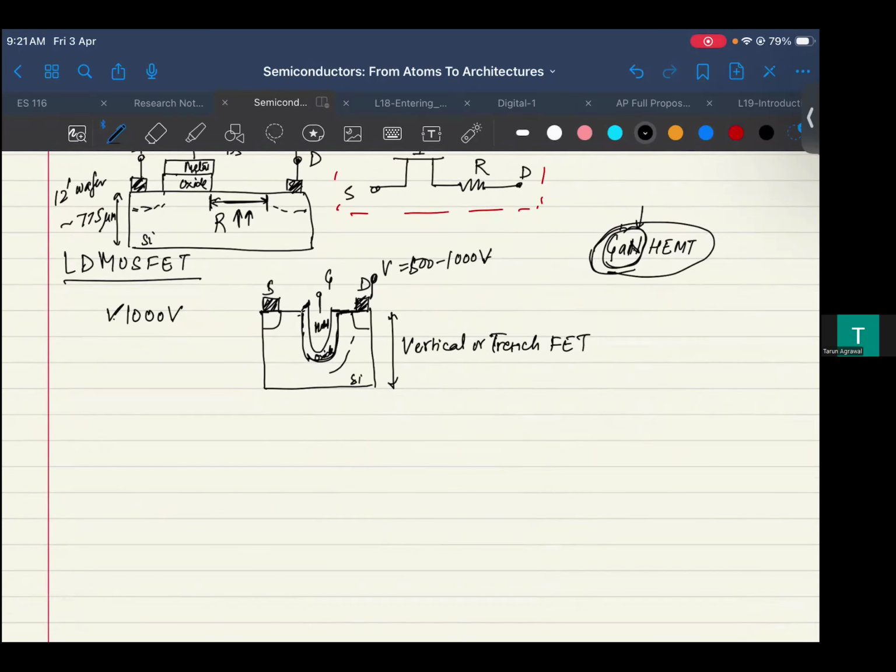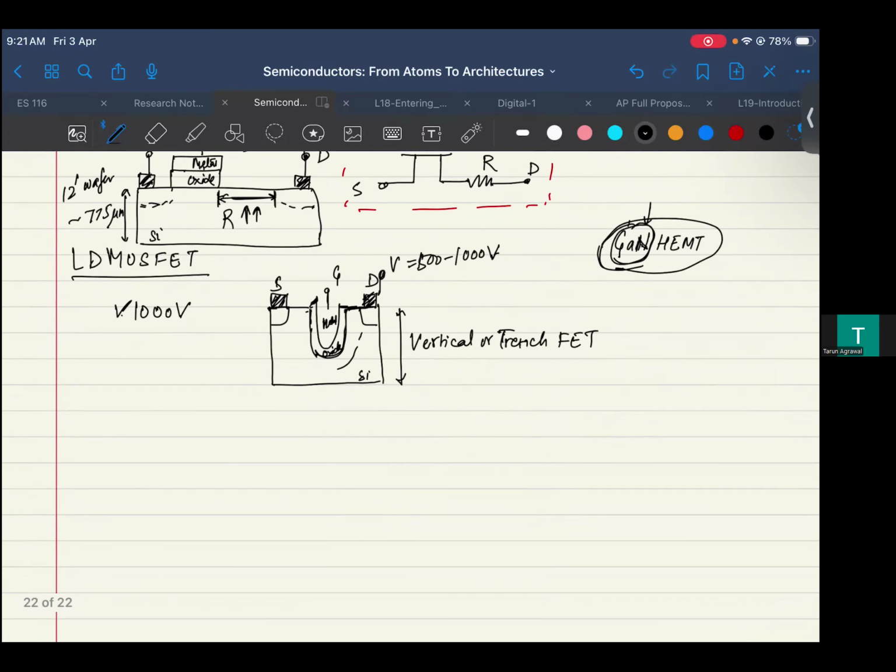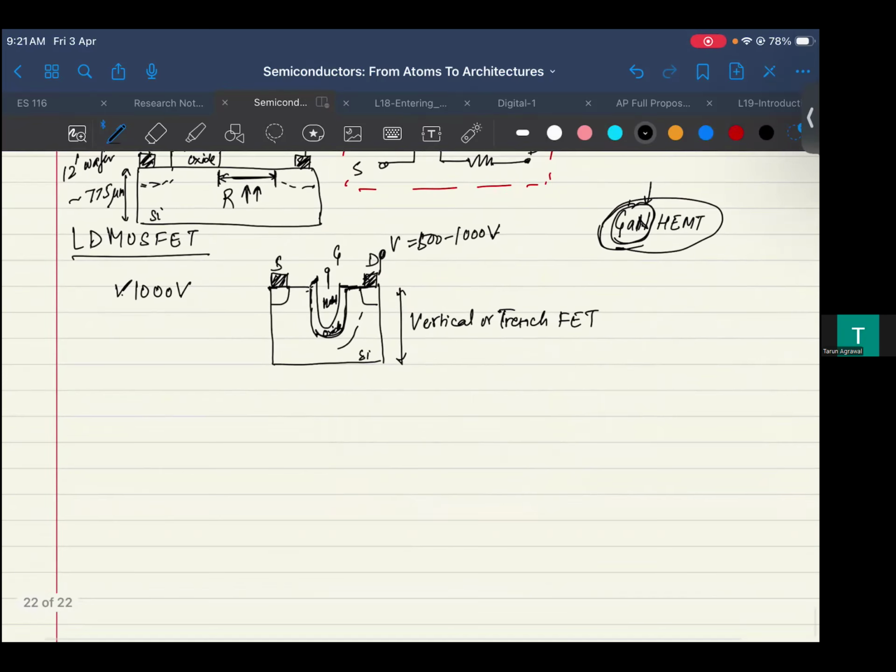What else is there? Is it only that, in the power domain, we use this functionality, or is it more than that? So we saw in flash also that there was a floating gate we could use. Similar to that, people are thinking, is there a way to store information in this transistor itself, right? There is a lot of work which goes on into this, because we talked about how this silicon can be seen as the DRAM cell, right?